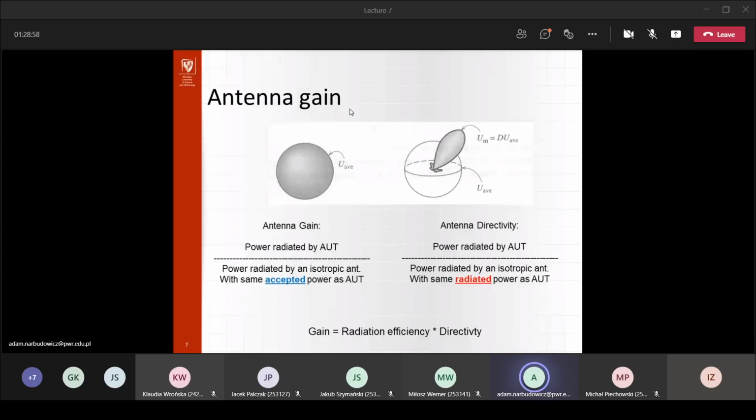So the important thing is that antennas, as a general rule, there are a few exceptions, but that's really marginal, from the point of view of applications, antennas are passive devices, right? So they can be modeled from the circuit point of view usually as RLC circuits. There is no way of a signal being amplified in the same way as with a transistor or a classical amplifier. Whatever you improve in certain directions needs to be taken from some other direction, right?